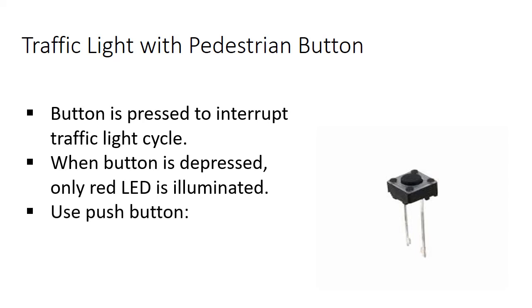This push button, it's got a button on the top, two legs that are both the same length. So it's a bidirectional circuit element. It can be inserted into the board in either direction. We just want to make sure that the two legs are not inserted into the same row, because then they would be connected to each other and you wouldn't be connecting them to other things.